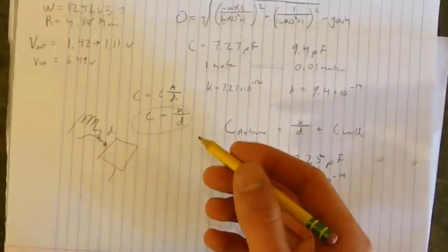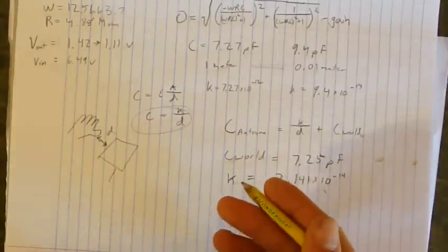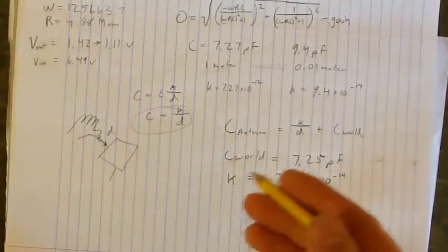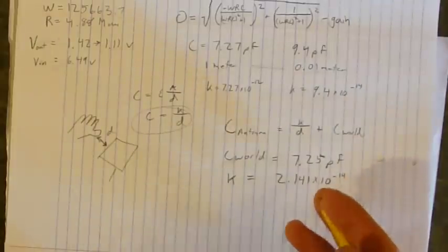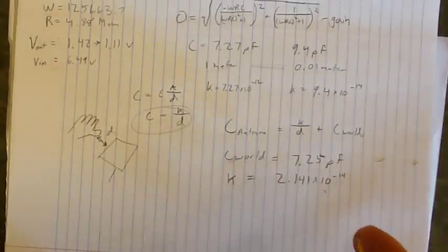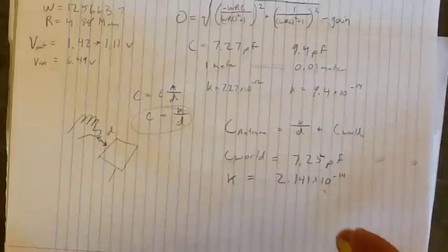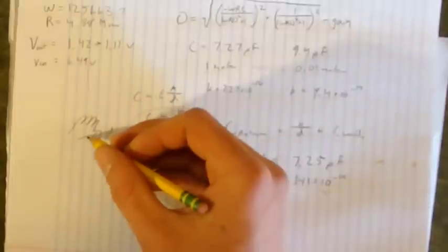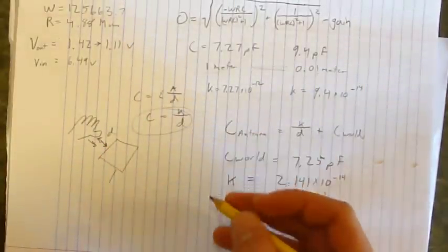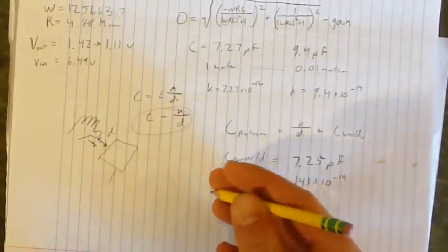It's actually logarithmic. So all of these different values are making this a very nonlinear situation. So we need to optimize our values so it looks like it's the most linear. We'll never get it perfectly linear, but we want to make it so that as our hand moves in, the change in pitch, or the change in tone, output by the theremin is very linear.